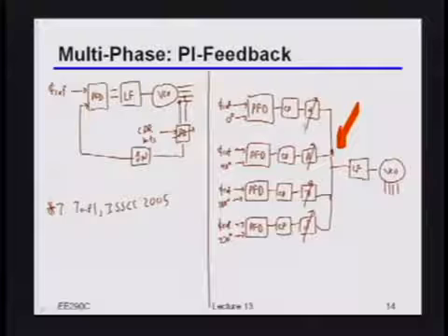So all of the weird transient junk and errors that I might be picking up here get smoothed out by working on that low bandwidth node. As you'll see, maybe not today, maybe next time, this is probably a lot easier to build than a really good phase interpolator would be. Because here, I'm really just working on average quantities, whereas when I'm dealing with a phase interpolator, you have to balance things just so nicely so that it really works the way you want it to.